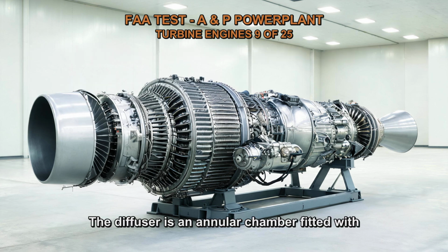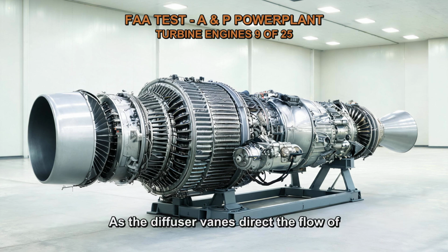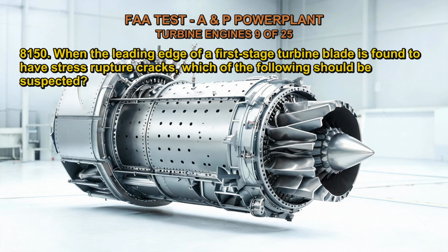The diffuser is an annular chamber fitted with a number of vanes that form a series of divergent passages between the centrifugal compressor and the burner section. As the diffuser vanes direct the flow of air into the burners, they increase the pressure of the air and decrease its velocity.